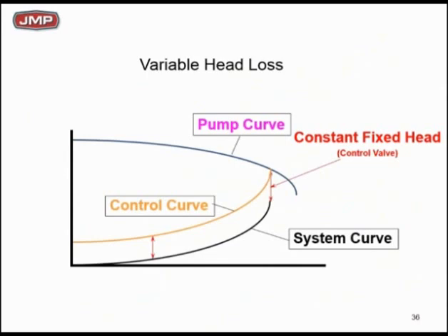That orange line represents the minimum constant fixed head required across that two-way valve, coil, and balancing valve to make sure I've always got enough differential pressure at that coil to give 100% flow through the critical zone, wherever that may be. So that means back at 0 flow on the left-hand axis, I'm not at 0 head, I'm at that minimum control head. So that control head is critical. That control head is the fixed head. That's the head we've got to deal with.